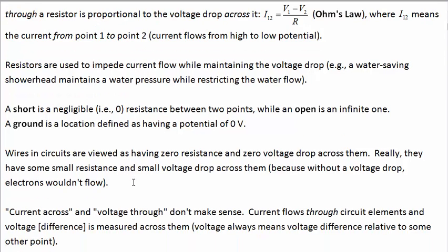Wires in a circuit are often considered as having 0 resistance, and consequently have to have 0 voltage drop across them, but they could still have some current going through them. Really, that's an approximation. Wires will have some resistance. And another thing to consider in a real circuit is contact resistance. Whenever you have a metal connected to another one, there's some resistance required to jump across that surface. So this contact resistance and wire resistance, depending on the circuit that you've got, is typically on the order of 1, 2, or 3 ohms.